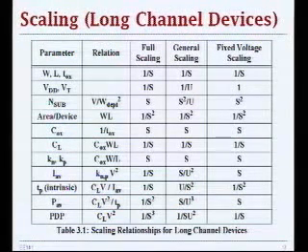For example, if you're looking for commercial off-the-shelf components from DigiKey or whatever supplier, you will see that today you can pretty much find everything that is compatible with 5 volt standards, 3.3 and 2.5. Maybe 1.8. Getting down to 1.2 volts or 1 volt, it's still going to take some time to get there.